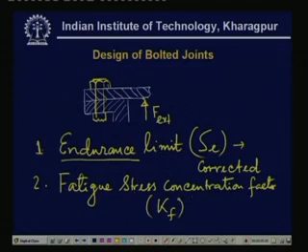We have the theoretical stress concentration factor, but when the component is subjected to fatigue loading, the fatigue stress concentration factor is not equal to the theoretical stress concentration factor, and we have to take into account what is known as the notch sensitivity. When everything is taken care of, we can find the fatigue stress concentration factor. Again, there are various values available for Kf, and those are given in the machine design handbook. So these two things are known. Now we can go for designing.